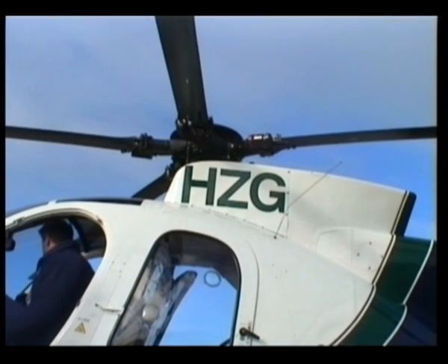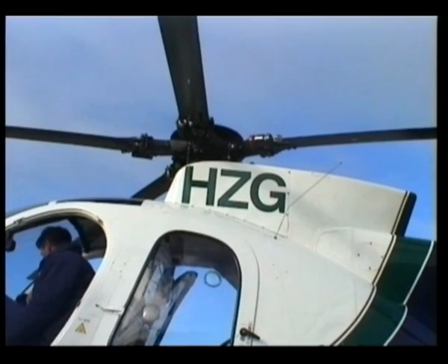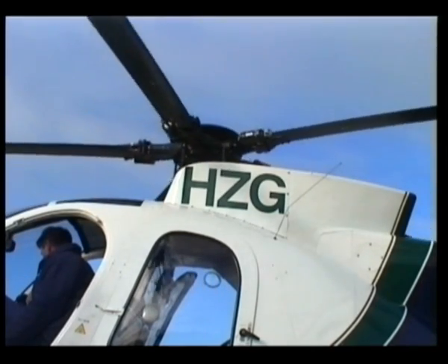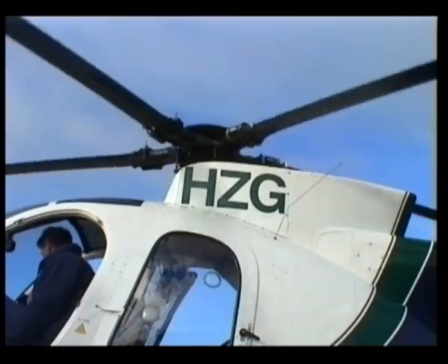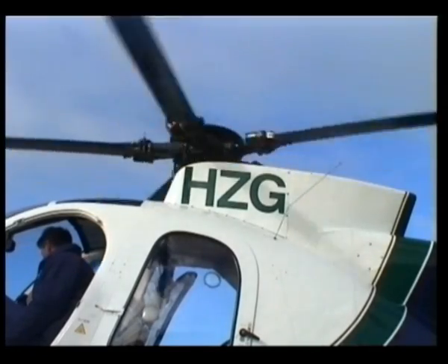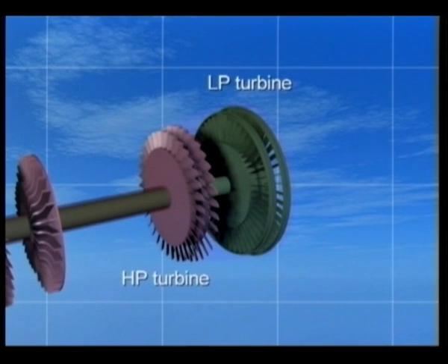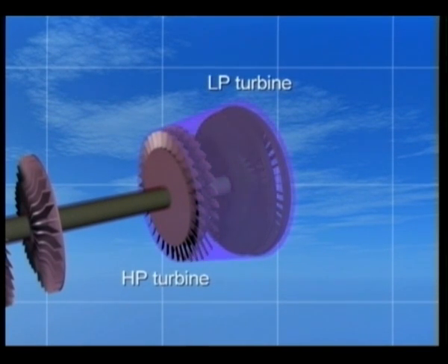Helicopter turbine engines, which have been with us since the mid-1950s, all have free power turbines in which one turbine drives the compressor and a different turbine drives the output shaft connected to the helicopter gearbox. The only connection between the compressor turbine and the power turbine is the main stream of gas, so each can run at its own best speed.